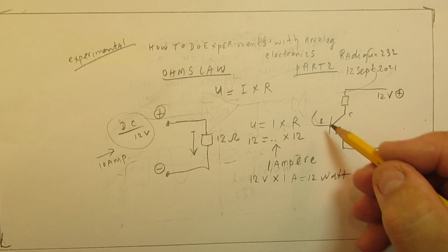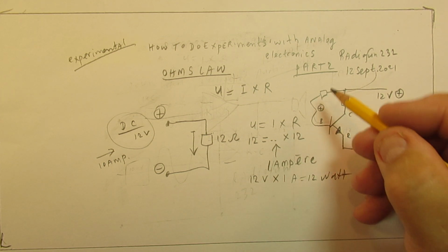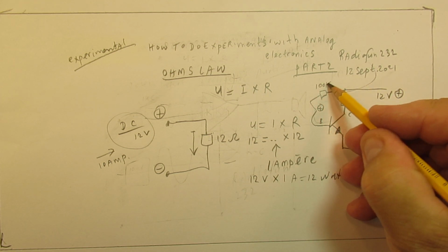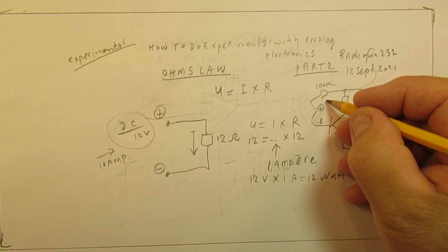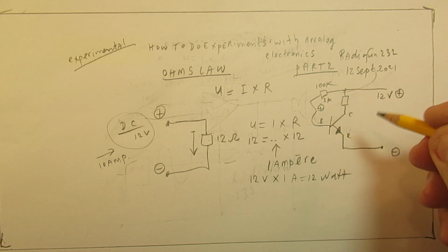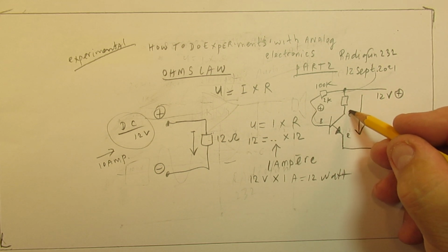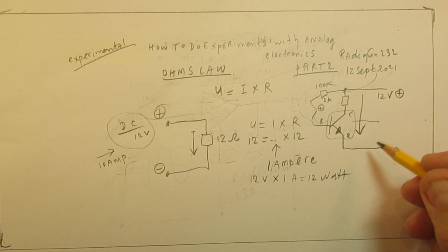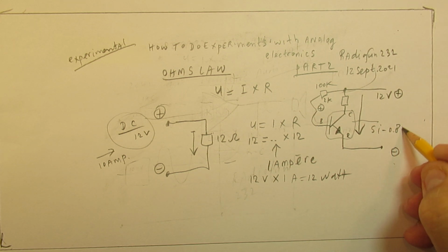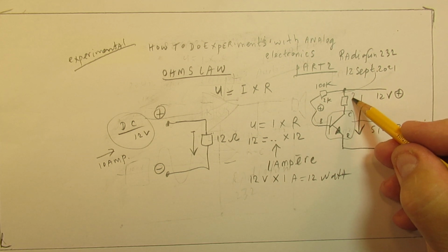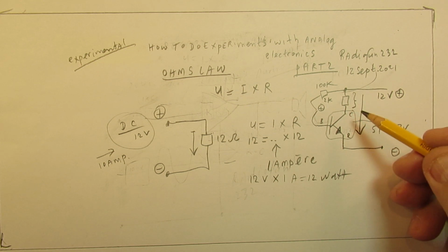When we set that transistor into conduction by adding a positive voltage here, this can easily be done with a resistor of 100k. When that transistor has a certain amplification factor of 50, no problem. Current starts to flow, the transistor gets into conduction, and the voltage drop here is low. Say it's a silicon transistor, then the voltage drop is approximately 0.8 volts.